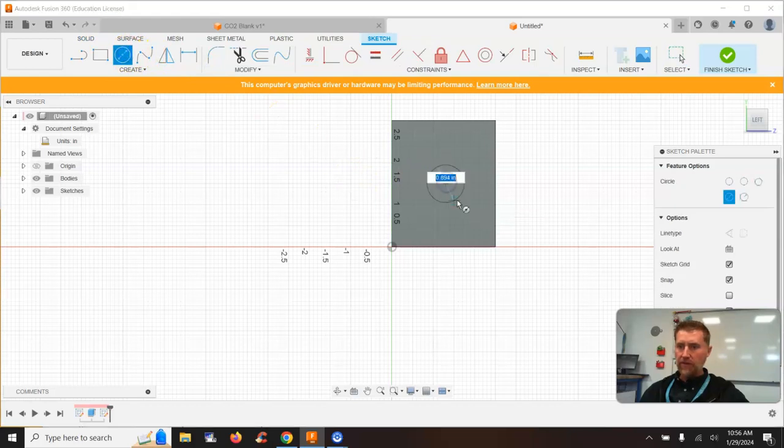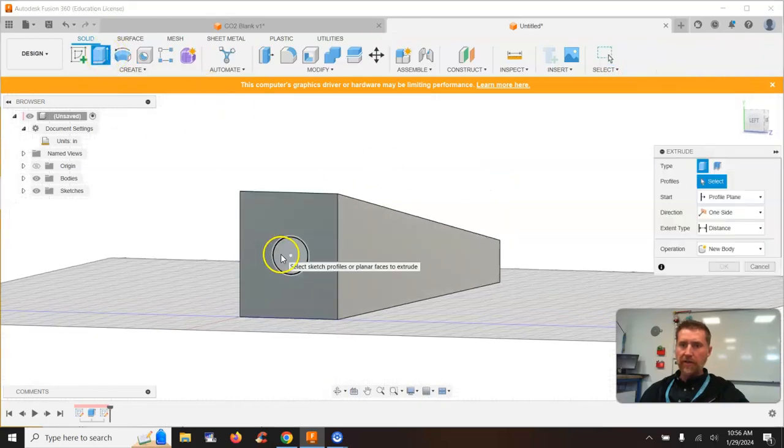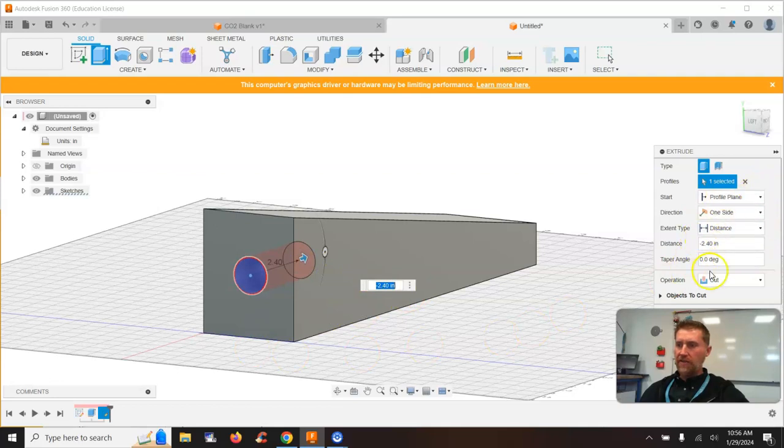I'm just going to create a little circle and extrude it in, and I want you guys again to make sure you use your correct dimensions. And I'll just pull that in. So there's no cut or there is a cut. In Onshape it's remove, or you can just drag it in and it'll automatically change. Or to make it a cut, we could also just say negative distance here.